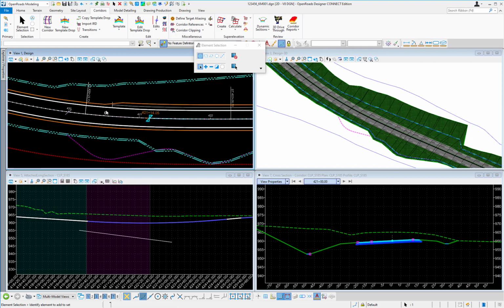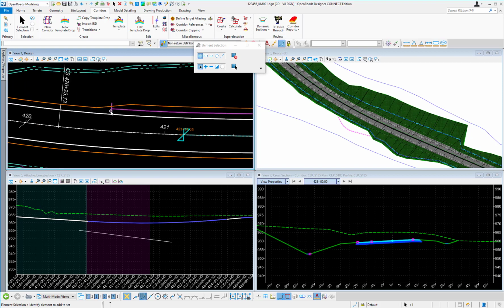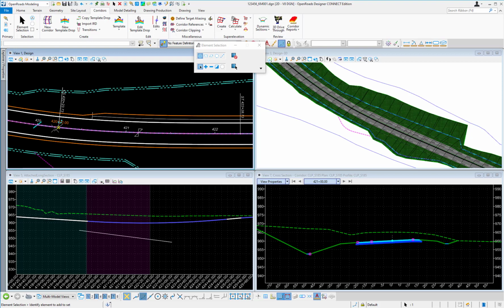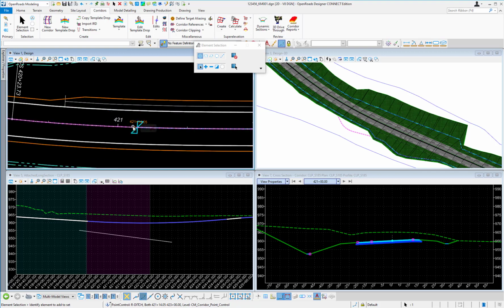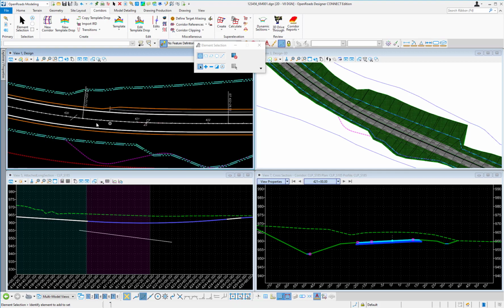But what you'll see, the difference is the horizontal line or the perpendicular line here is just a horizontal constraint. On the left ditch, where we only had the vertical point control, that just has a diagonal line. Now, when we have our ditch on the right, we see the two diagonal lines create the little crisscross here. We can modify those graphically, but to modify the start and end.